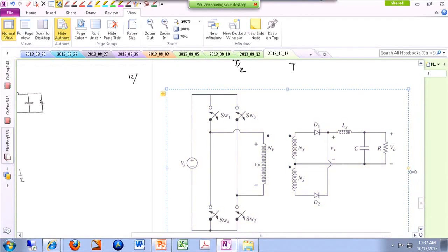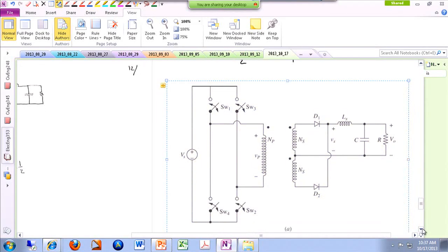All right, so look at this one and just consider that switching pattern that I just talked about. So one time I turn S1 on and S2 on together. What happens is, if you look at this primary side voltage, it's the same as Vs. So I'm applying a positive value of Vs or Vin to the primary side. And the loop is basically this loop.